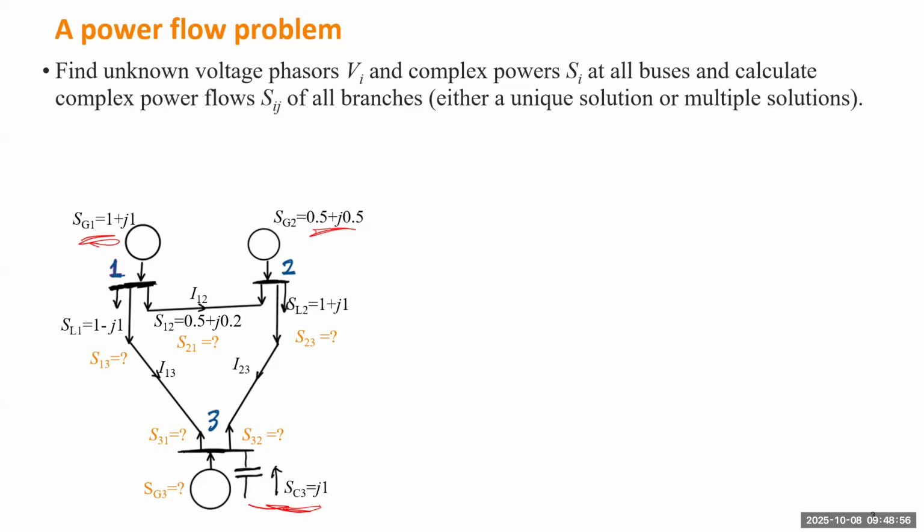So for instance, it gave you some line flow. Because we assume the voltage magnitude everywhere to be the same, and if you go back to that slide, actually we proved the active powers sent from both ends will be opposite to each other. That makes sense because if each line is lossless, whatever you send from bus 1 will be completely received at bus 2. If you define the direction from both terminals, their numbers have to be opposite to each other. And the reactive power will be equal.